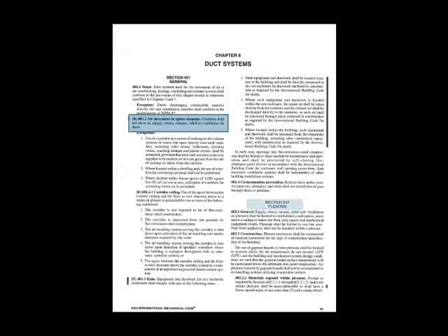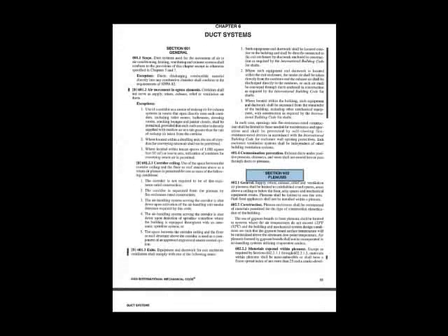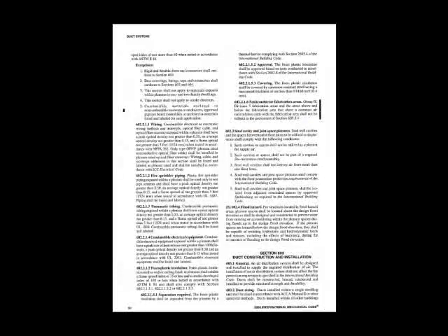Section 602 talks about plenums. It talks about general requirements of plenums. They are limited to one fire area, cannot cross firewalls, and cannot have any fuel-fired appliances installed. This is because of smoke movement. Plenums are the main ductworks that come off of and return air to the heating and cooling systems. It talks about the construction of plenums, the materials that can be used in the plenums, wiring, sprinkler piping, pneumatic tubing, and combustible electrical equipment. It talks about foam or plastic insulation and semiconductor fabrication areas. Again, we have to be very careful with plenums because they can catch on fire, they distribute smoke, things melt, things burn, and they have extreme temperatures.